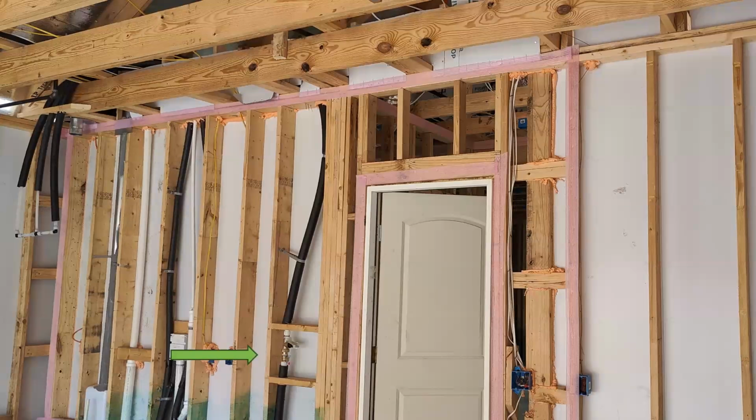So some builders take it to the next level. They actually picture frame around the garage wall. That's what I was saying. We're picture framing the floor above, if they've got a conditioned floor above it, but they're picture framing the garage wall. So before sheetrock or sheathing goes up, they put gasket all the way around the doors, around any openings, around any gaps. The green arrow is showing where they framed the valve box, and it reduces the chances of air transfer in and out of that cavity. They've got foaming on both sides, which closes that gap between the piping, and then they've got it framed.